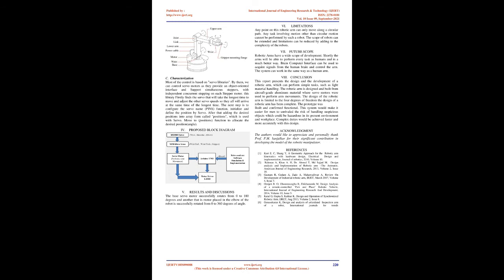Rotary, prismatic, hook, spherical. The rotary joint is described by the angle theta about the z-axis, the prismatic joint by linear displacement d along the z-axis of the joint, the 2 degrees of freedom joint is described by yaw and pitch. The spherical joint is described by 3 rotation axes, as in the wrist and shoulder.